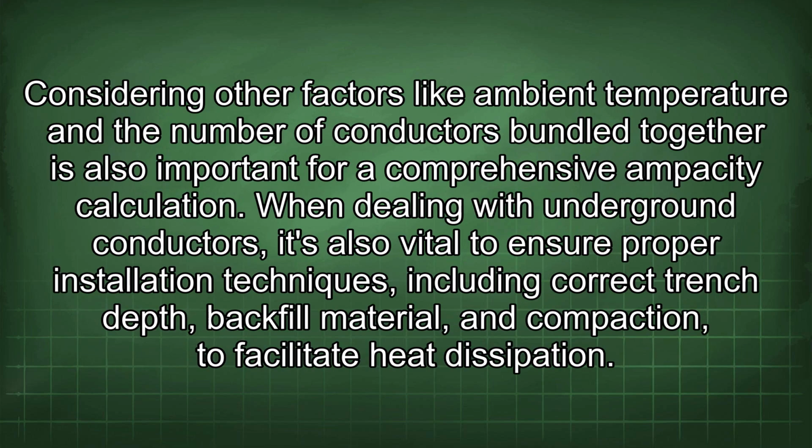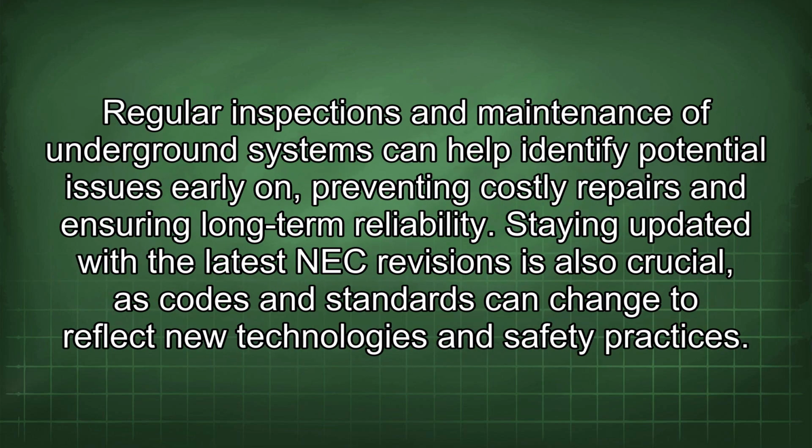Considering other factors like ambient temperature and the number of conductors bundled together is also important for a comprehensive ampacity calculation. When dealing with underground conductors, it's also vital to ensure proper installation techniques, including correct trench depth, backfill material, and compaction to facilitate heat dissipation. Regular inspections and maintenance of underground systems can help identify potential issues early on, preventing costly repairs and ensuring long-term